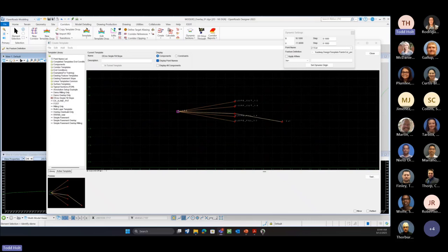So the next thing that we're going to do is we're going to create our ditch to control that. So we also talked about in that PowerPoint different ways of controlling our end condition. And we can add parametric constraints, we can add point controls into those to force it to be a more dynamic end condition. So even end conditions can read parametric labels, which are parametric constraints. We're going to build our ditch template to do that.